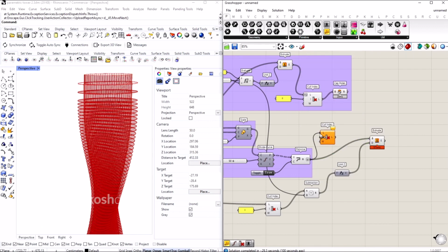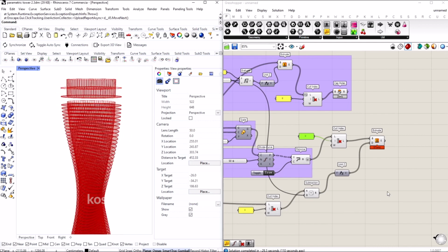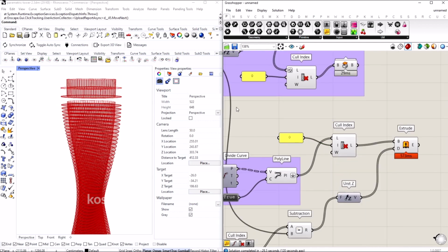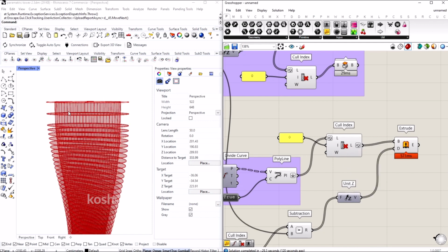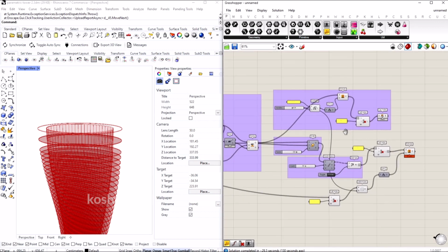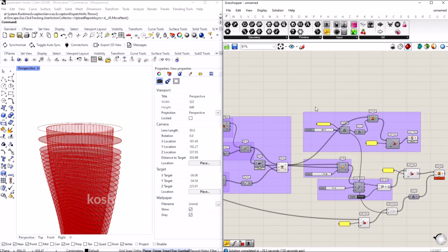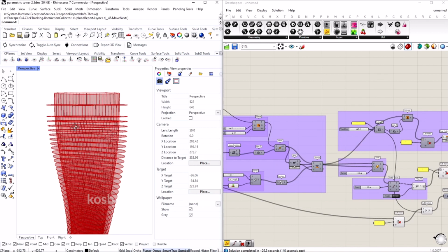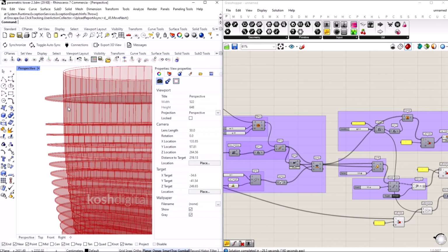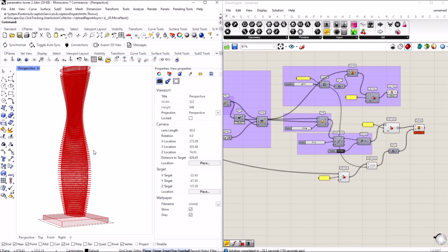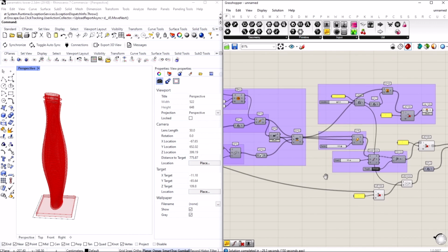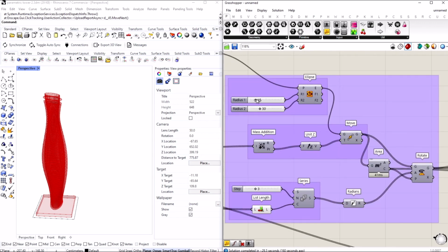We'll go back and cull. So input this. Now cull index, maybe we'll just say 0. Okay, because it has two different curves, it's taking from the reverse this, and even the output also reverse it. It will work. Now it is working. Okay. Switch off the preview. Even this polyline also, let's switch it off. So now you have the tower. Okay, so if you go ahead and play with shape of the tower,